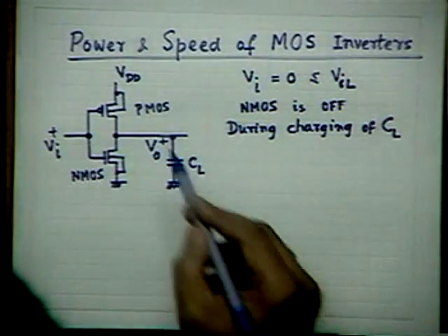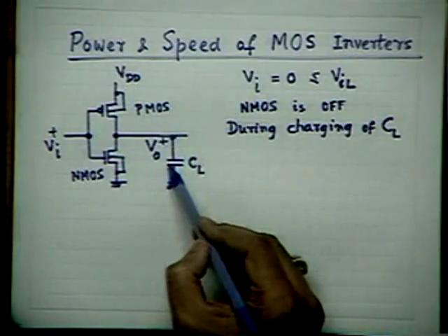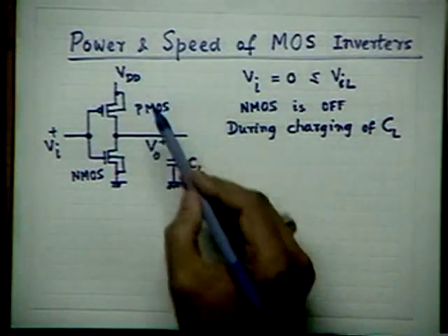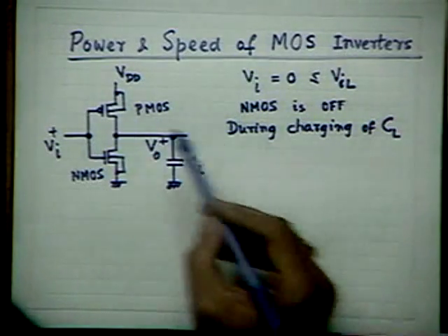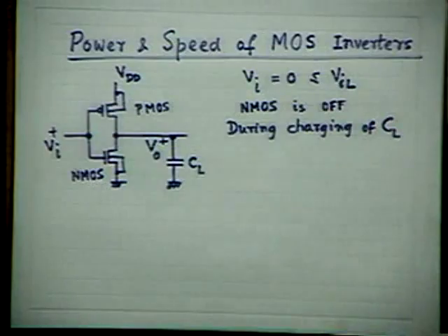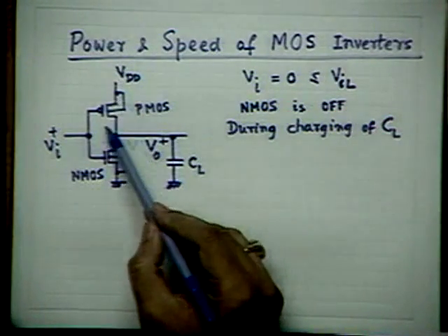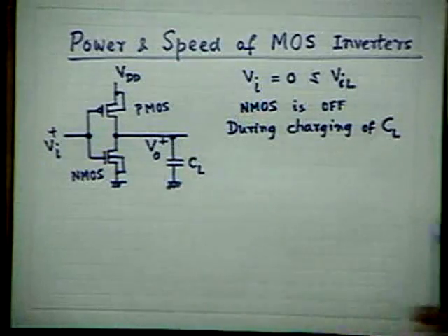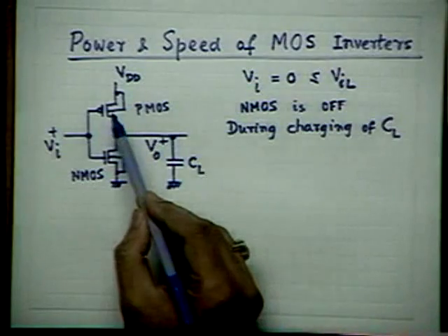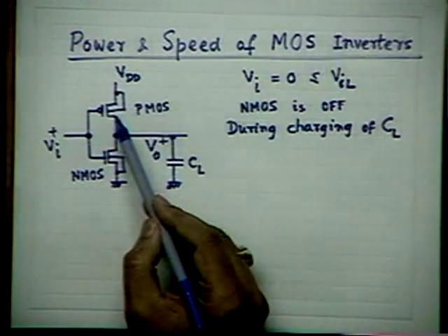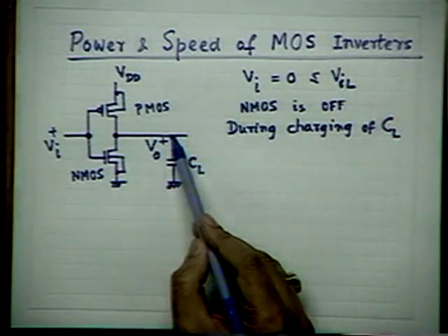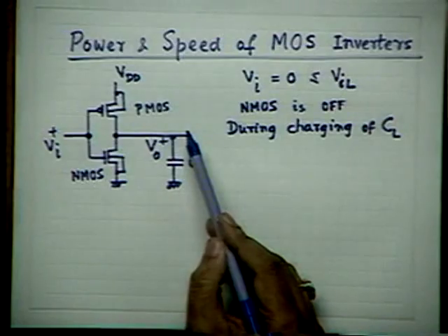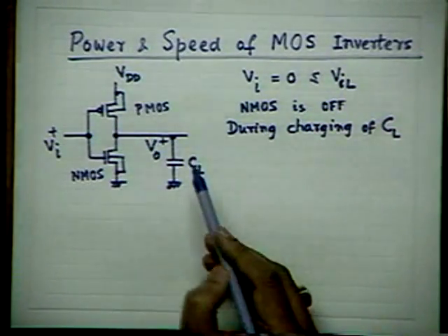you know that the energy which is dissipated, because CL is getting charged through this path from VDD, this is off. So this is basically an RC circuit. The only difference between an ordinary RC circuit and this RC circuit is that this R is continuously varying with time or voltage or current, a non-linear resistance, whereas this capacitor is an ordinary linear capacitance. So be it almost a short circuit or any R, it does not matter. We have to see ultimately this capacitor is charged to what voltage. Depending on that, we know there will be the power dissipation. This power is actually dissipated in this resistor.